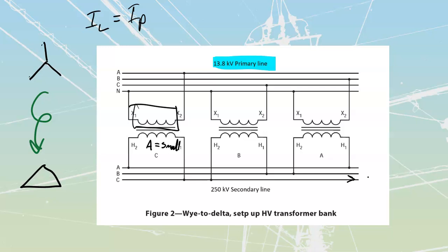The other thing that we're going to have issues with is that each of my lines is now going to be a fairly high voltage type of line, and my phase windings, my E line and my E phase, are going to be the exact same, which means that I'm going to have thicker insulation around each of these windings over here. I'm not going to go through all of the calculations for example number 2.